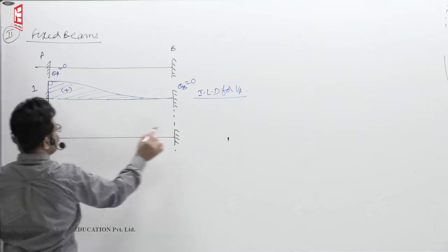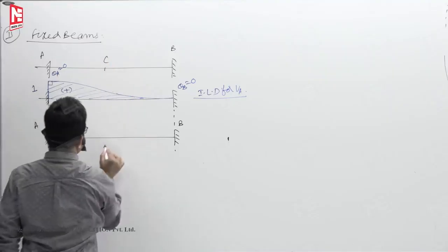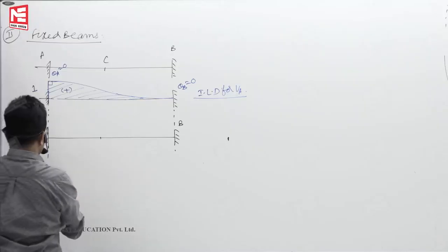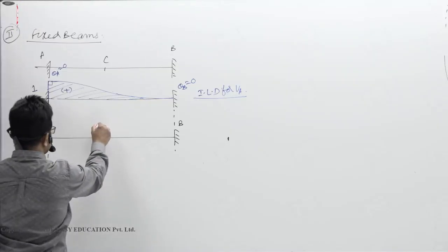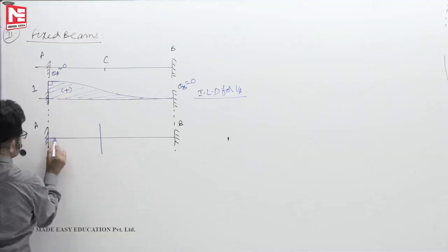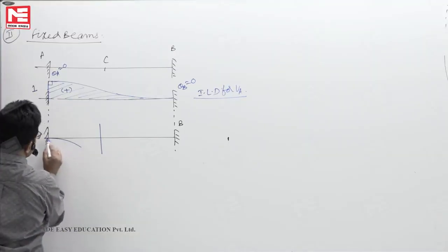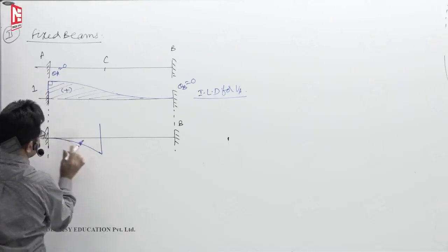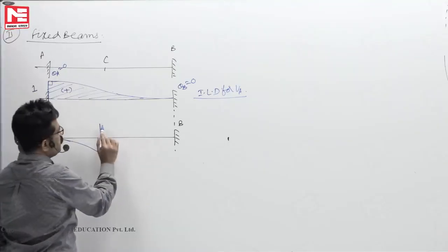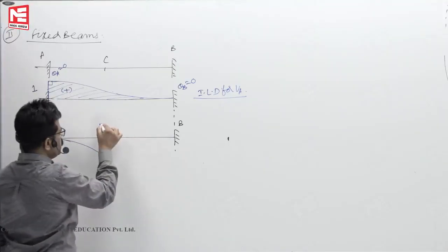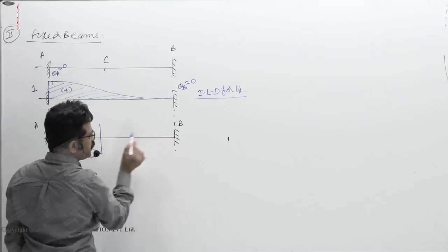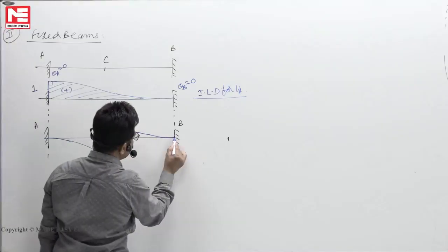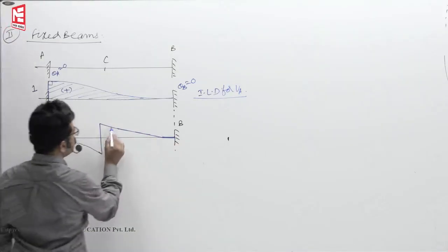Without removing the supports at A and B, somewhere C is here say. Cut the beam, left portion push it down, right portion lift it up. So that total ordinate again becomes 1 like this. And here the difference is, if it is a propped cantilever, it went up like this, now it will go down like this because slope has to be 0 here. So to maintain that 0 slope, a smooth curve can be drawn like this only.